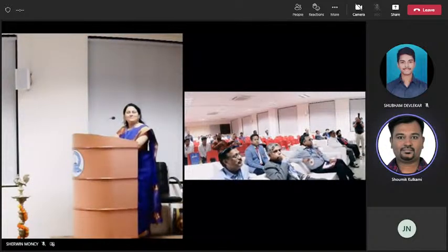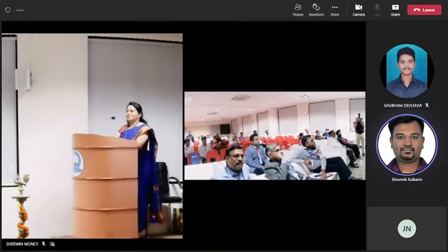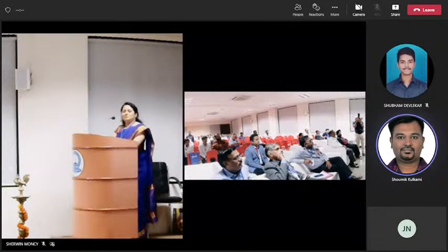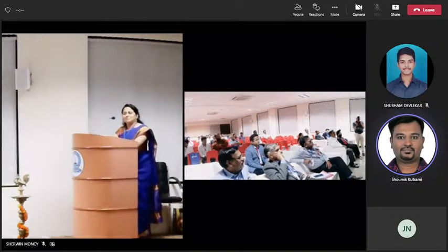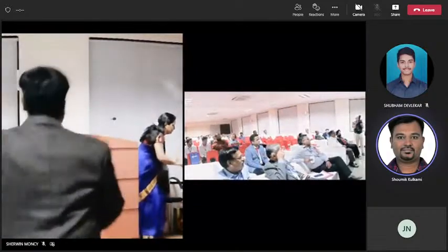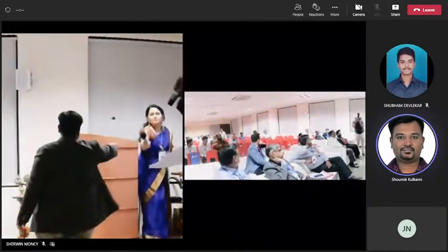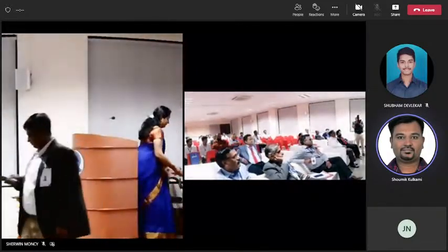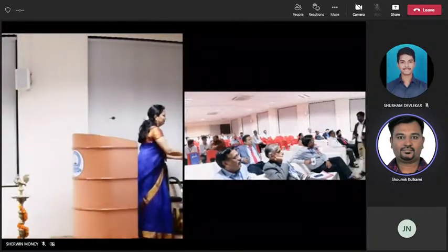What is the fault frequency in case of a journal bearing groove defect? If anyone knows the answer, please raise your hand. Other than Pallavi, yes sir. 6x is the right answer, 6x of operating speed.